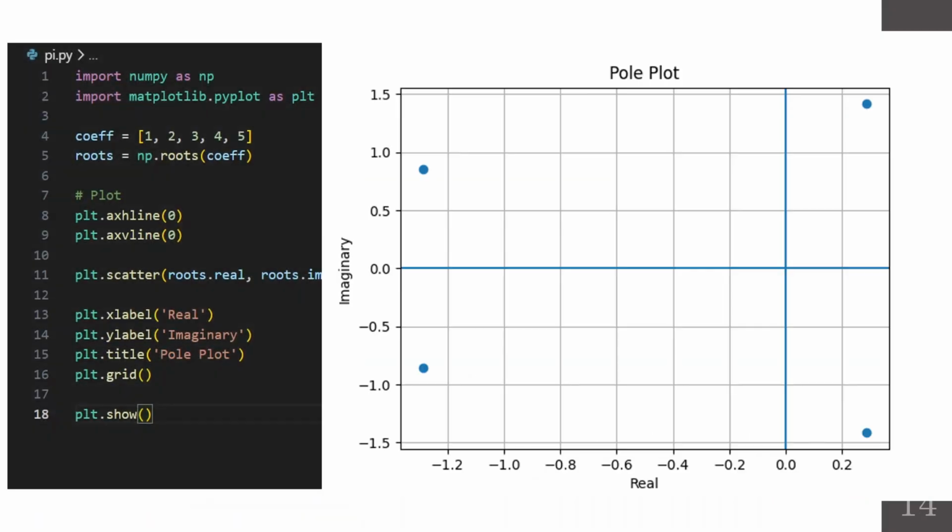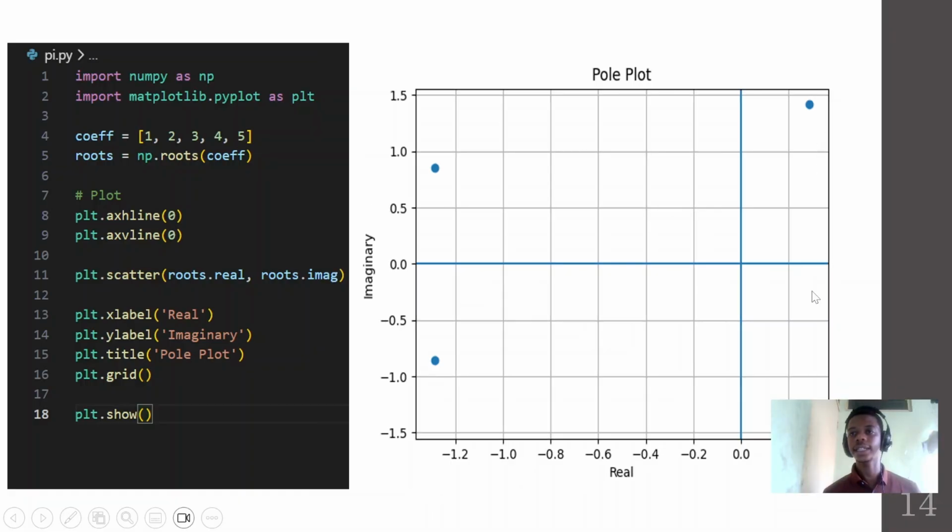When we plotted our graph in Python, we saw that two poles lie on the right half plane. Because the two poles lie on the right half plane, this makes the system unstable. The number of sign changes in the first column corresponds to the number of roots in the right half of the complex plane, so because we have two sign changes, we have two poles in the right half plane. If we had 3 sign changes, we would have 3 roots on the right half plane.